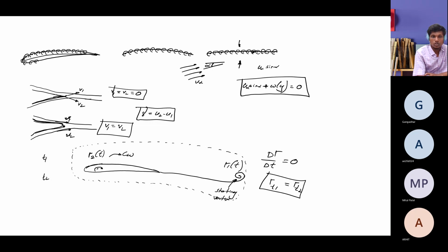But if you see the individual airfoil alone, there is some presence of lift because of the free stream, that is u infinity. This free stream creates a bound vortex, or a presence of lift on the aerofoil. This we call a bound vortex. With this bound vortex, you are getting a lift by using the Kutta-Joukowski theorem, that is lift is equal to rho infinity u infinity gamma. As gamma is coming from the bound vortex, you are getting the lift on the aerofoil.